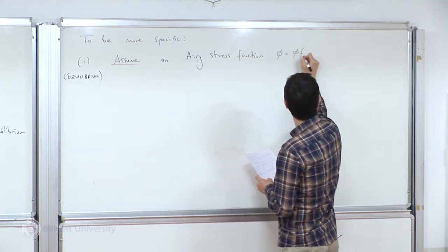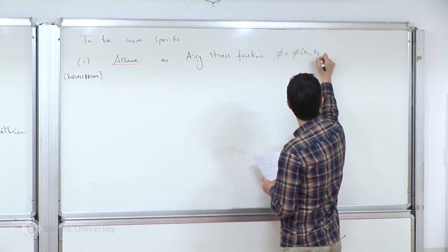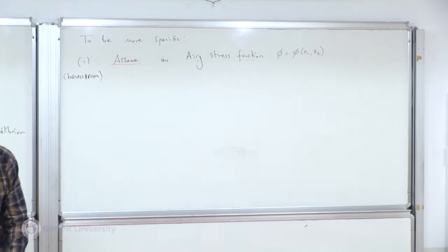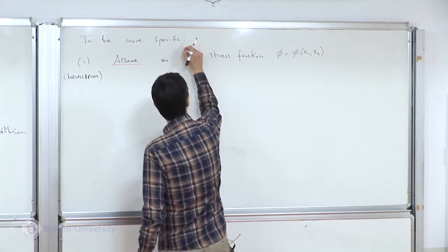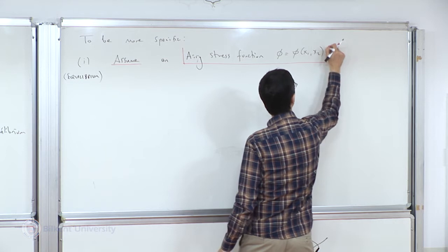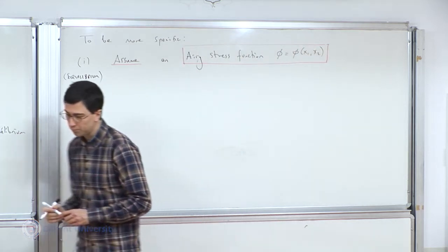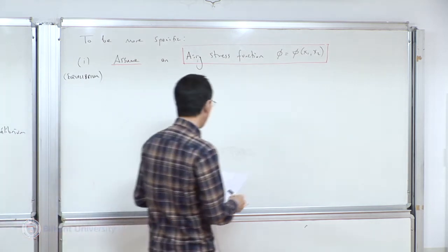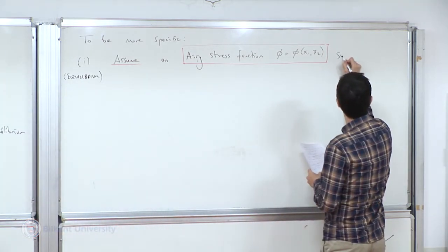And remember, we live in a 2-dimensional world presently. The 3rd dimension is just a byproduct. If we need it, we can work with it. But the solution lives in the x1, x2 plane. Okay? We assume an Airy stress function such that.